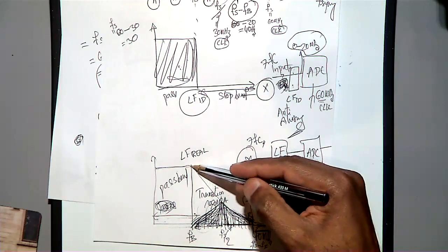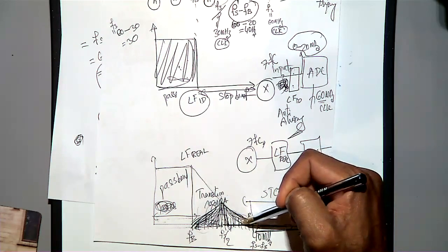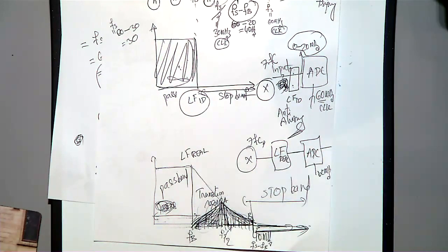Then what you can do is you can make it much sharper. Then you can increase the number of poles. But then when you increase the number of poles, what will happen is you are using extra op amps. Your second order might become sixth order.